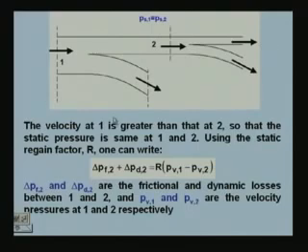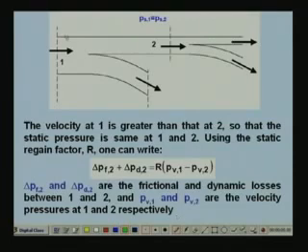Let us say that this is a typical duct run. Let us say that air is coming here and you have one branch here, and then you have the upstream, I am sorry, downstream and the branch. Okay. So, what is done in this method is, for example, if I am talking about the downstream, you have velocity at section 2 as V2, let us say, and the velocity in section 1, that is upstream, is V1, right. So, what is done in this method is V2 is reduced, that means V2 is less than V1.